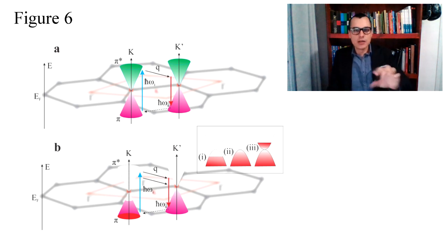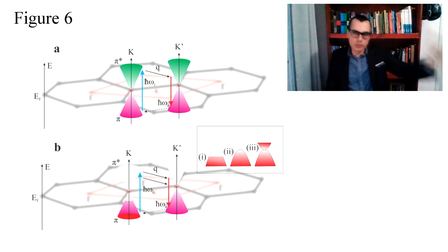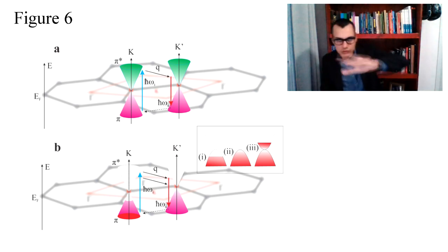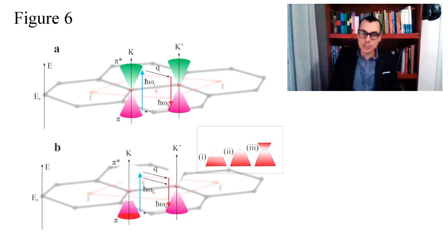Imagine that, like in the classical semiconductor case, when a slight variation occurs in the electric field due to adsorbed cations on the carbon-based material with niobium surface, to conserve the number of particles and to fulfill the overall electrical charge neutrality, the Fermi level has to move away from the mid-gap position.